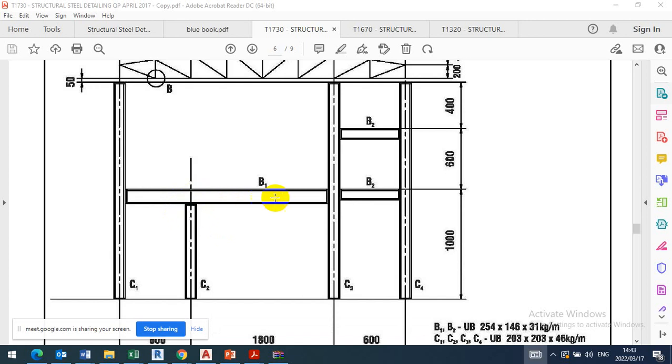When the beam is sitting like this, you have to know that this white piece here is a web. The top piece, which is dark, is the flange, and the bottom part is the flange. When you go to the side of beam 1, you must show us the I-beam. You will see the shape of the I, which is the I-beam, which is also the same here. So we understand on the beam. And what they said is when we are doing the detailing, we must show the column centers.